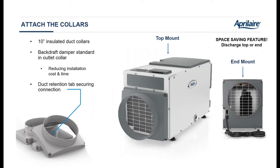If you're going to be ducting it, we include collars. Like I said, there's a backdraft damper built into the outlet collar. The collars themselves have some molded tabs on them to make it easier to attach flex duct. Makes it easier to trap the flex duct and get that zip tie tightened down on it, cinched down on it. I want to point out a really nice feature. The discharge side, the outlet, can either be coming out the end, so it's like straight through the dehumidifier, or it can come out the top. That's field adjustable. You can see there's a collar and a blank off plate.